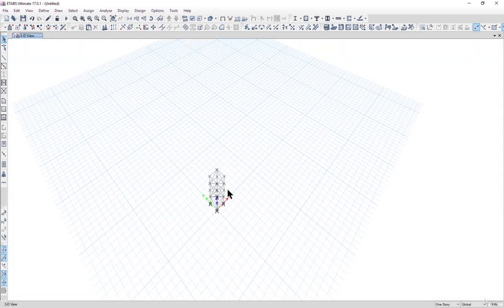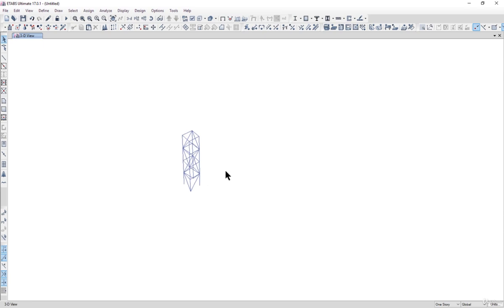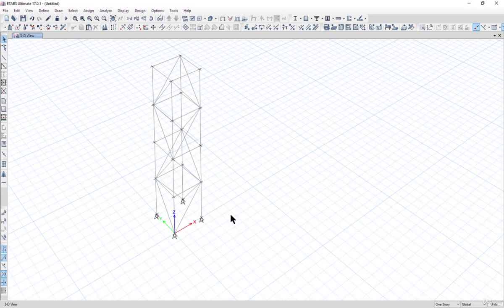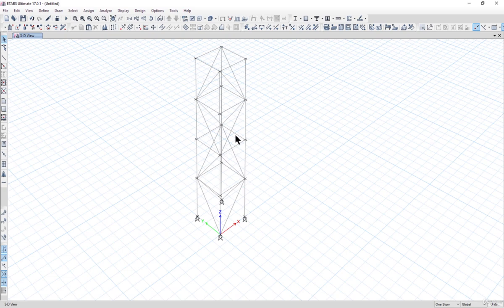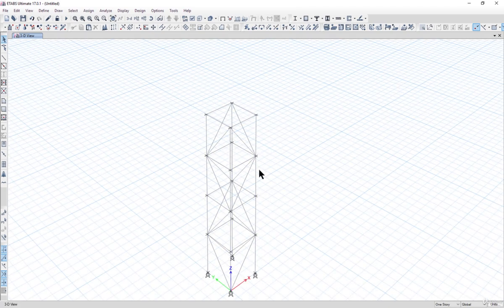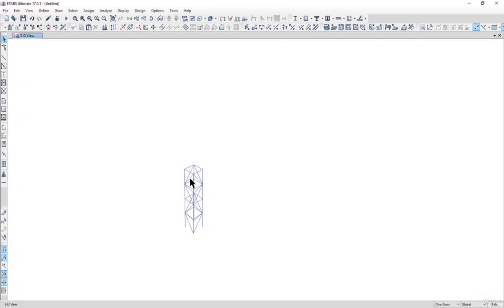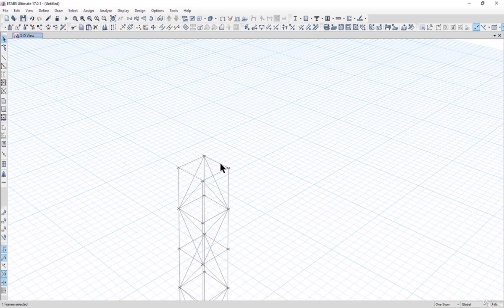So we can check in the 3D view whether whatever we have done is correct or not. This is a very fine arrangement of the horizontal members and bracings. It's like we have tied this whole arrangement of the 4 columns and beams with bracings. After that, what we need to do here is add a joint.